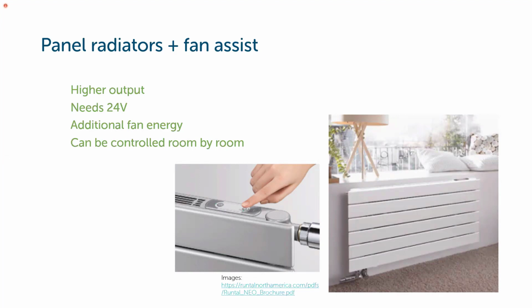Again, you've got the surface area of the hydronic coil within the unit itself, and then a fan blowing air across that to distribute air further into the room. I didn't cover here the other radiant options, which can be wall panels or ceiling panels. So there are many creative ways to provide distribution with low temperature water within the building.